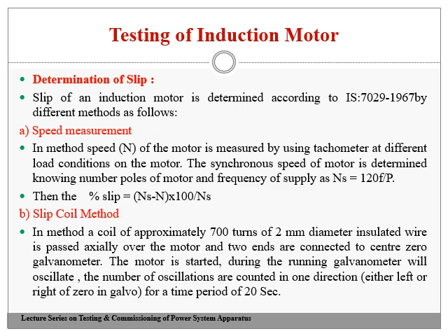Then, knowing the synchronous speed as well as the rotational speed of an induction motor at a different load condition, we can find out the slip at which the induction motor is operating. That is given by (Ns minus N) into 100 divided by Ns. This is the first method of determining the slip of the induction motor.